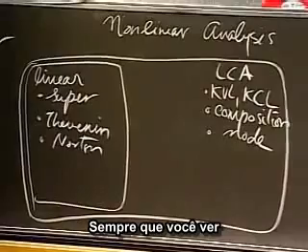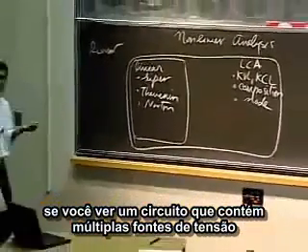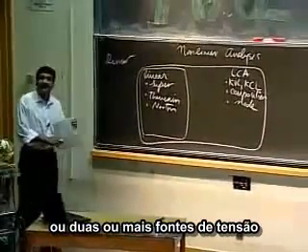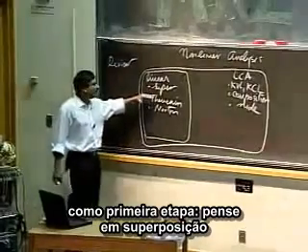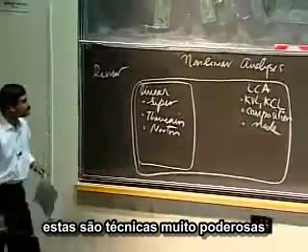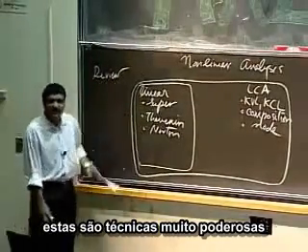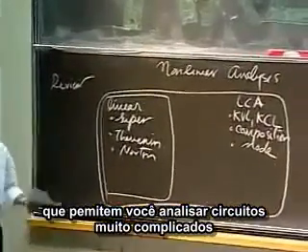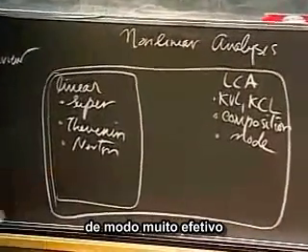If you see a circuit containing two or more voltage sources or current sources, as a first step, think superposition. Okay? And these are very powerful techniques that let you analyze very complicated circuits very effectively.